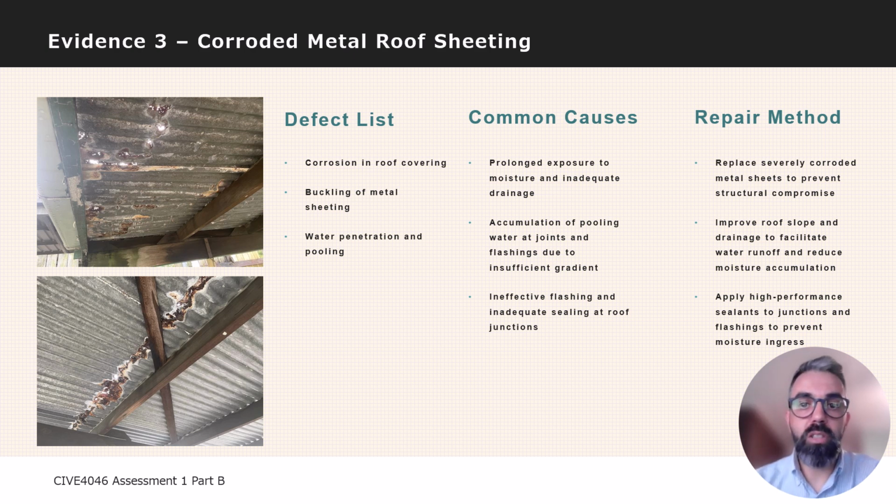Issues to consider include ensuring compatibility of materials with the existing structures and the risk of ingress during the repairs. The estimated cost will account for procurement of the corrosion-resistant materials, labor to install and replace the sheets, and the application of the protective coatings.